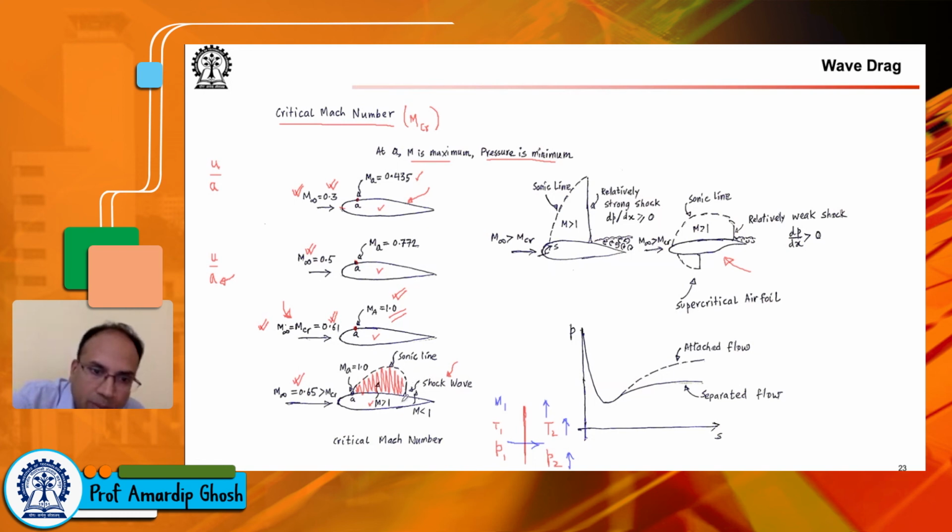So flow separation happens, and if you think of that idea of attached flow and separated flow, that caused pressure drag due to flow separation, something similar is happening here, where the pressure distribution in the aft part is actually quite high, and the flow separates downstream of the shock wave, creating this separated region.